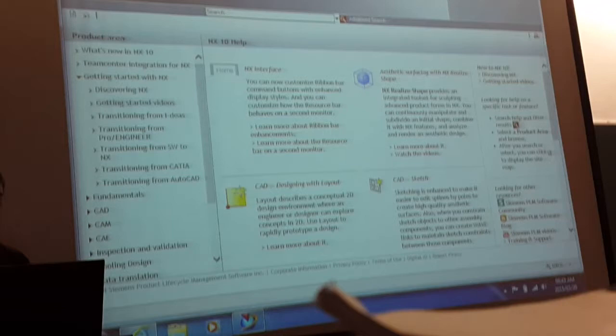Right, so if you were dealing with a complex part, in the next phase of this operation you could move on to an idealized part model, right, which is copied from the initial part, and you're able to make manipulations to that part without impacting your initial CAD model. Right. Once the idealized part is created, you then move on to what we call a FEM model, finite element model, right?